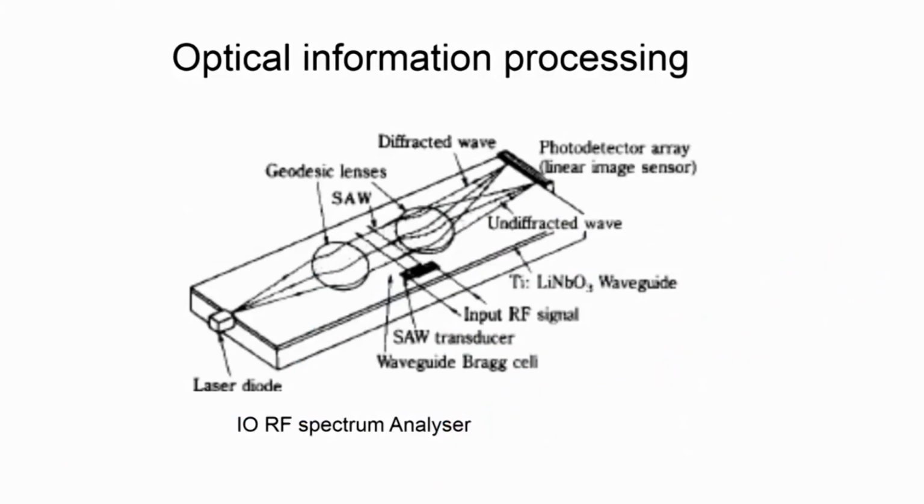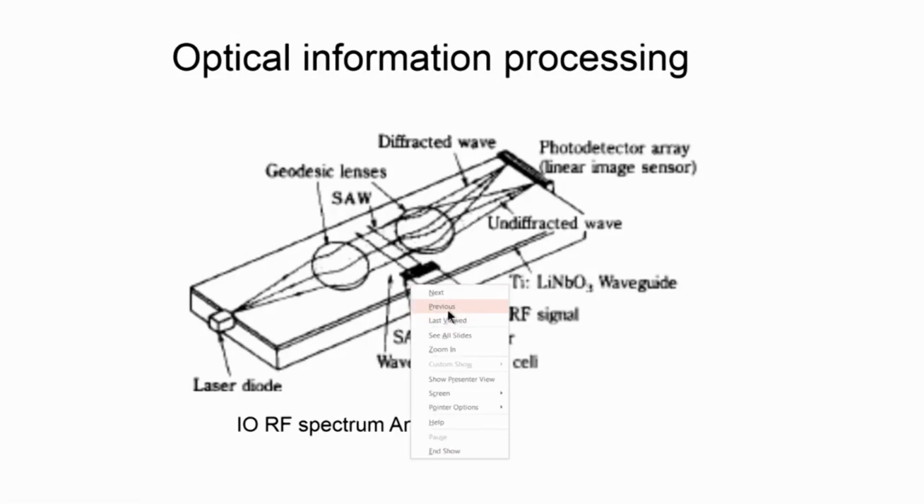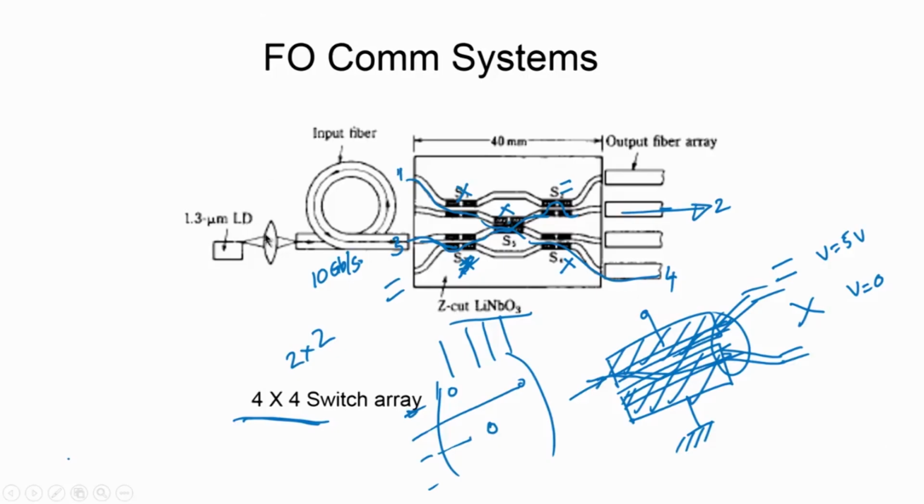and the signals are modulated at 10 Gbps. Typically laser diode transmitters are used, and at the output, if you want to detect the signal directly, you can put photodetectors. Of course, many times, up to 10 Gbps, you can also use direct modulation of laser diodes.